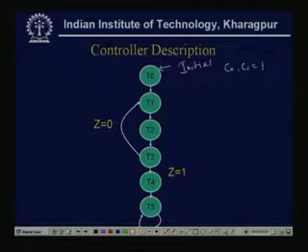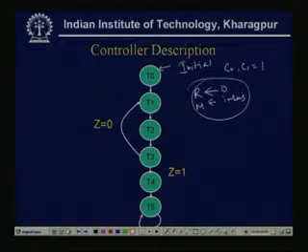Now, the operations R is reset, R is cleared, and M assigned to inverse are carried out with the trailing edge of the next clock pulse. So, the controller moves to state T1 with this clock pulse, that means after initialization, after one clock pulse, these two operations, R set to 0 and M set to inverse, will be performed.